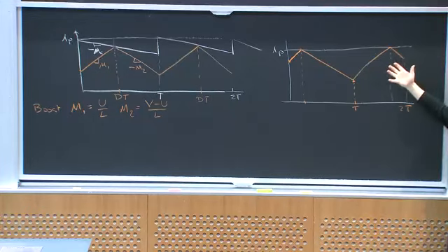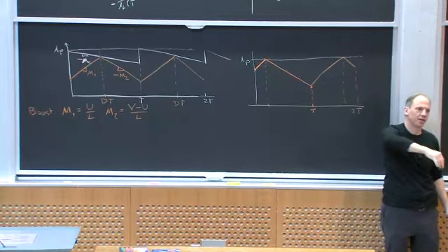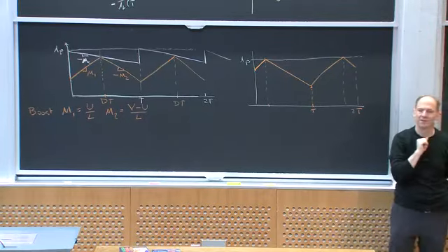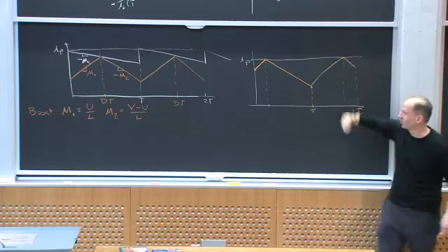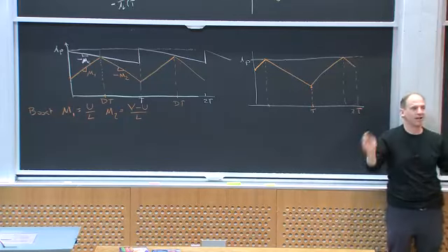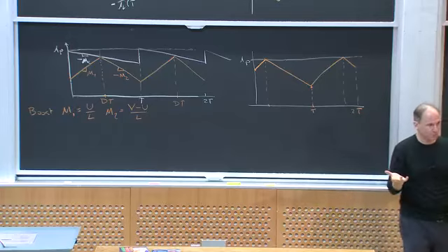In some examples, it won't settle down at all. It'll just bounce around chaotically. I mean, literally chaotically. Now, is that a problem? Well, at the highest order, it's not. I'm still controlling the peak current. My output loop will still regulate and everything. But it is problematic from other perspectives.